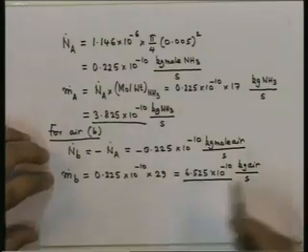The diffusion rates or the leak rates are pretty small. They are of the order of 10^-10 kg per second. That means even in 1 hour we will lose something like 10^-6 of a kilogram. 10^-6 of a kilogram is 10^-3 of a gram, that is of the order of 1 milligram in 1 hour.